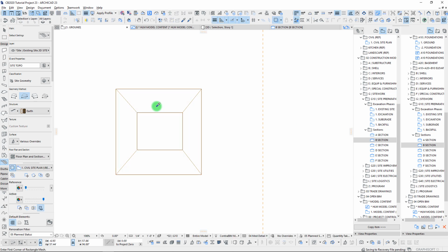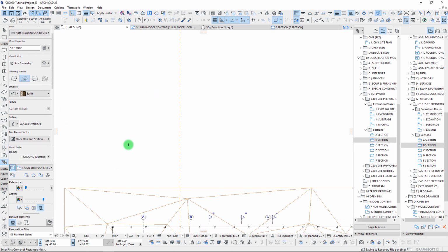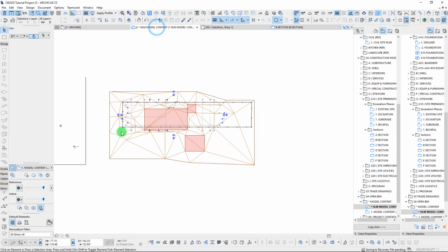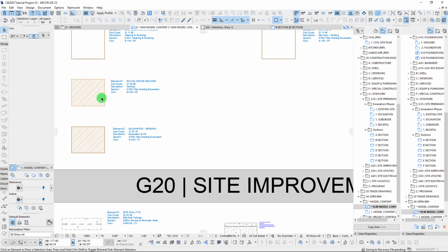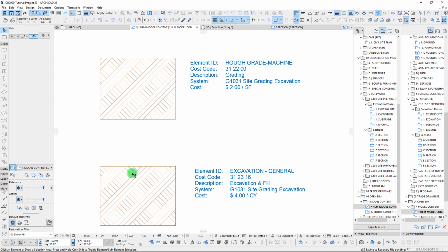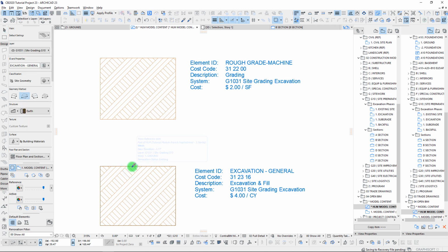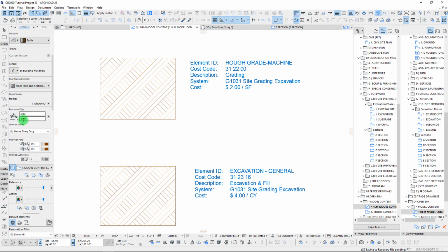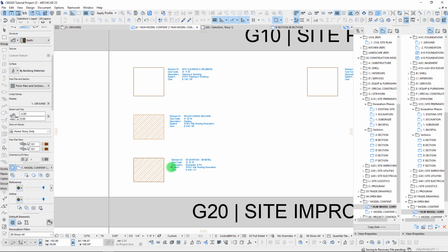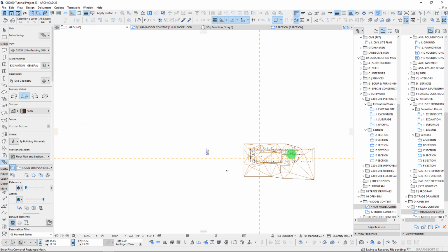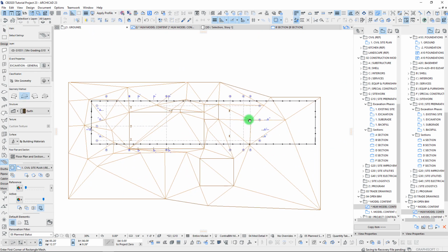So okay, with that, let's pick up the settings. Actually, you know what, we are going back to our module. We will be picking up our excavation general, and within here let's set this to -5 feet to begin with, not 53 but -5 feet, and let's set this to 0, and we'll go back. Now it's time to start modeling in our excavation.